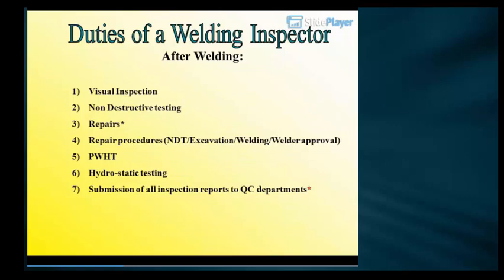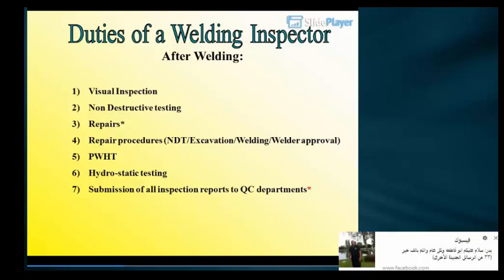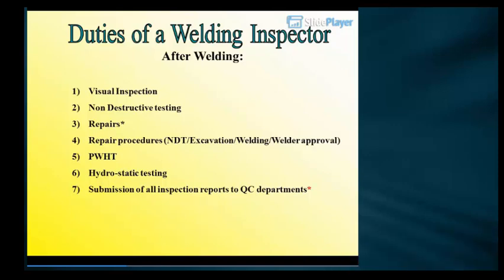Duties of a welding inspector. After welding. Visual inspection. Non-destructive testing. Repairs. Repair procedures: NDT/excavation/welding/welder approval. PWHT. Hydrostatic testing. Submission of all inspection reports to QC departments.